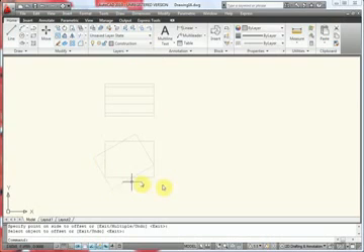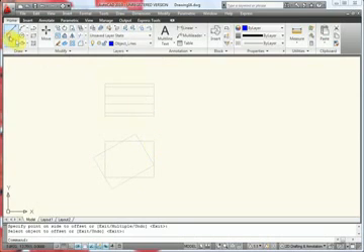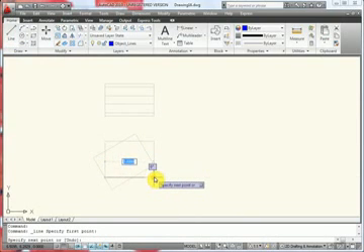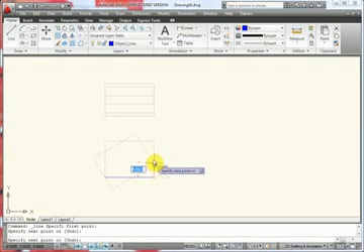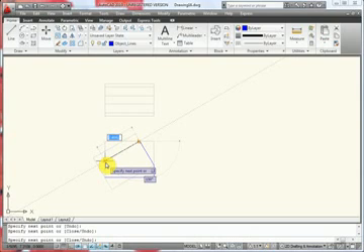And now I want to start filling in some geometry down here with actual object lines. So I'm going to switch to our object layer and go to our line command. I'm going to start with this lower left-hand corner point, and I'm going to kind of reference the drawing in the book. That way I choose the correct shape or the correct points that I've drawn in the construction lines. And this last point down here needs to be perpendicular to that back line or the intersection point on this vertical line. And then I'm going to close the geometry.